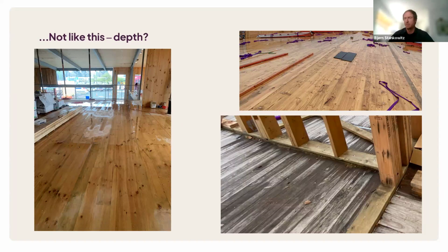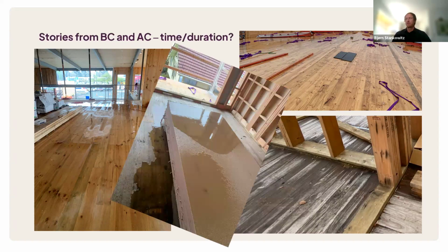We don't really want to start like this, but unfortunately, these are a few shocker slides, I call them. Looking at mass timber projects where, unfortunately, the moisture management hasn't gone the way it was agreed, or the rain actually came in and it was unpredictable, and it was out of our control because the area was too big. And then I remember a phone call from a builder asking me, what do I do with this gib? It's been sitting out in the rain for a while, which has triggered in return a whole lot of questions coming after that, because the timber around it was at fiber saturation, and therefore prone to sag under the additional weight of the gib,